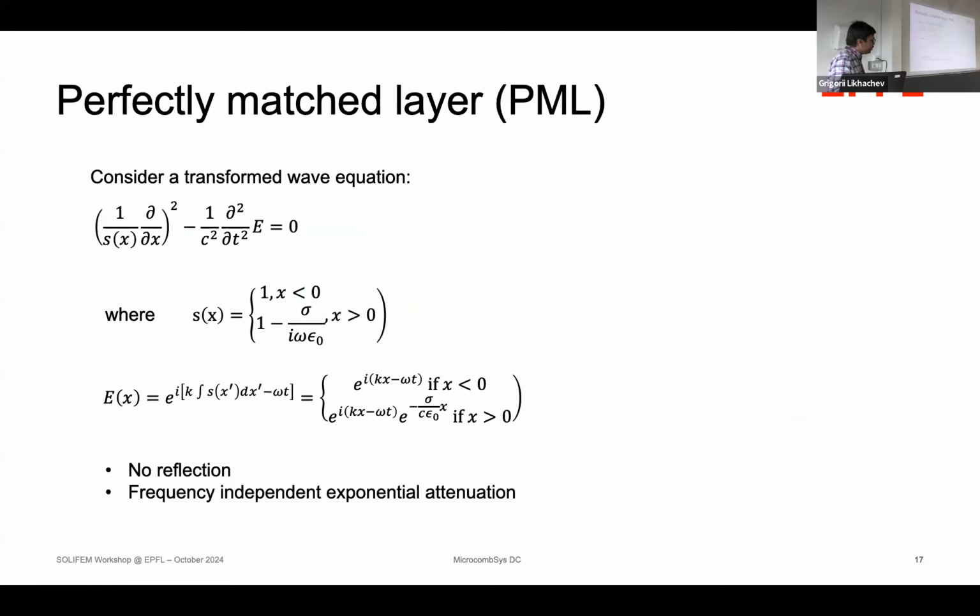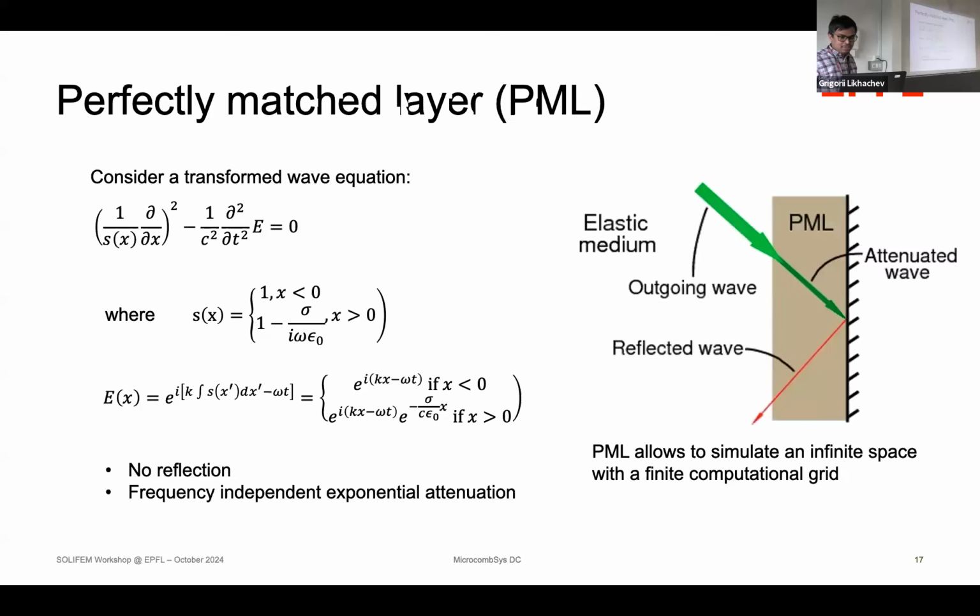So this is one of the examples. The thing that we'll be using in our session today would be a perfectly matched layer. What the perfectly matched layer does is it absorbs all the electric and magnetic field components that are going to be incident on your surface, and it is going to attenuate the field. And no matter what angle of incidence your field is going to hit the perfectly matched layer, there will be no reflected waves emitted from this.